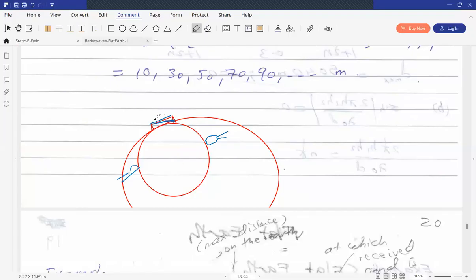So this means that to obtain a straight propagation, we need to increase the radius of the earth. They calculated the increase. It was a factor of 4/3. So we have to multiply the actual radius by 4/3 to obtain the effective earth radius. I do not know if it is clear now.